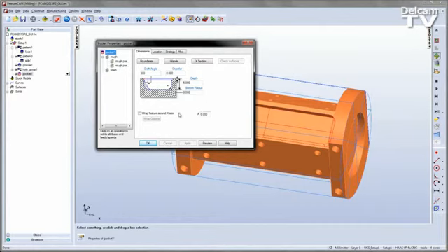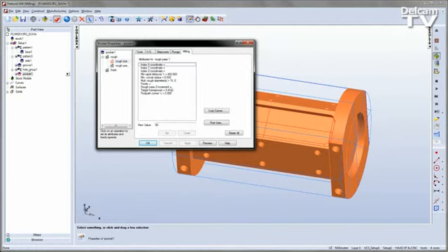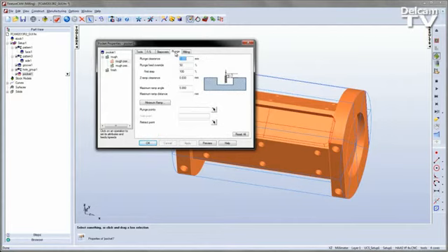However, we have added some new improvements to this. If I go over to the roughing operation, you can see again a reflection of my tool dialog as we saw in the tool manager. But note there is a new tab called plunge. We have basically extracted all of the plunging options and ramping options and placed those into a plunge dialog. This plunge tab has different controls for different elements such as the plunge clearance, Z ramp clearance and so on. Anything that isn't available, you'll note, is greyed out.